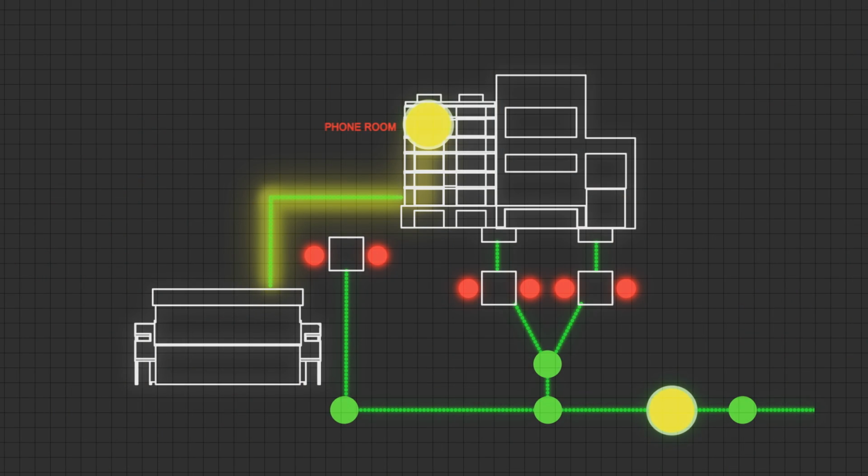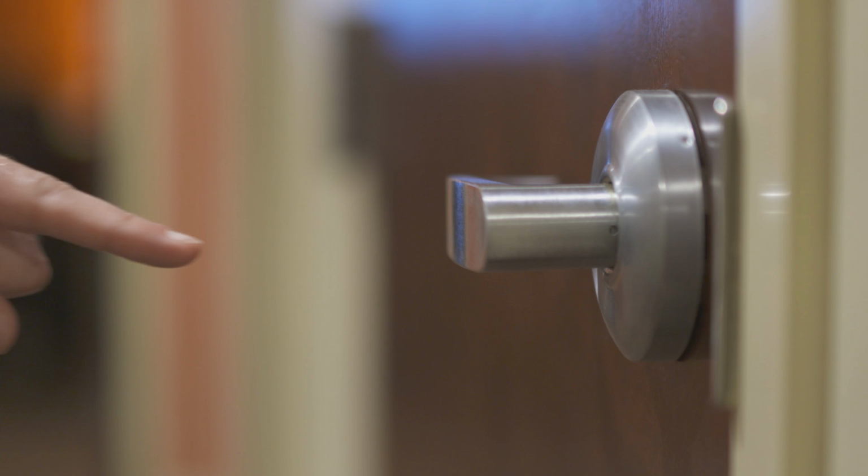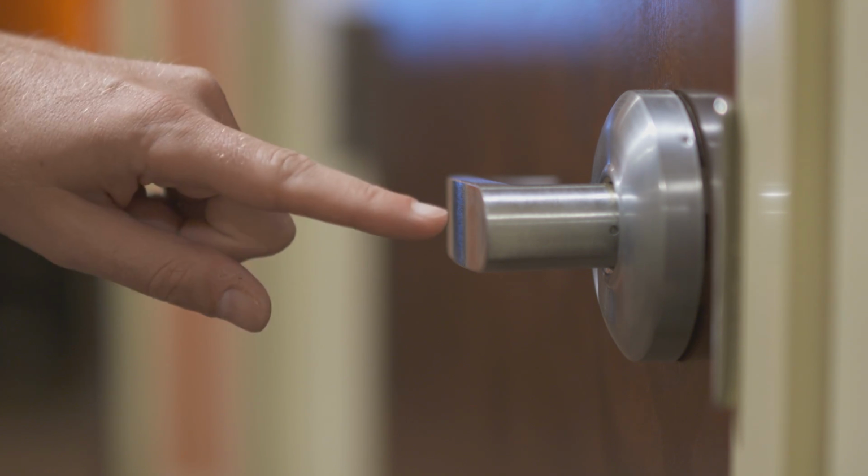that was the spark over, and the discharge, well, it's kind of like if you rub your feet on carpet and you build up a static discharge. You know, when that discharge occurs, you have a spark, but in this case, the spark caused a flashover, and then the 60 hertz current came through with a fault current and blew up the equipment.